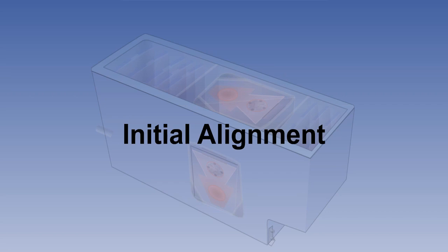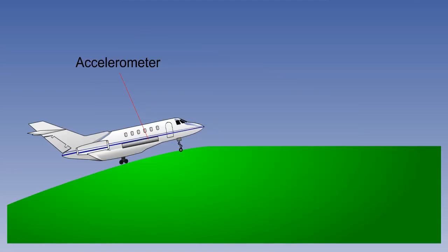The axis transformation system needs to establish the horizontal level and the direction of true north, just as the platform in INS did. Here is an INS-equipped aircraft with a platform parked on sloping ground. Here is its longitudinal axis. During the levelling phase of alignment, the platform and the accelerometer mounted on it would be driven down to the horizontal.